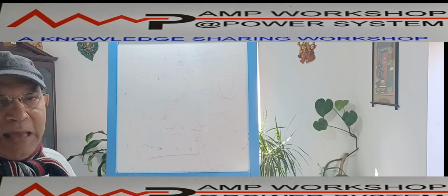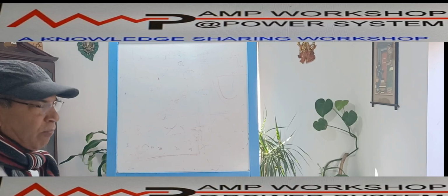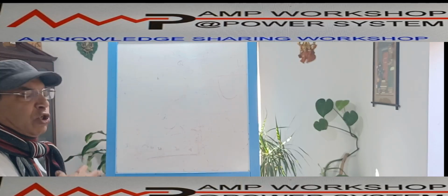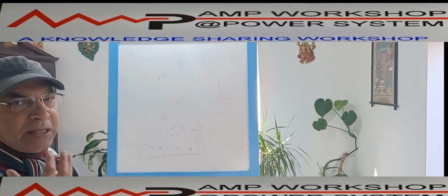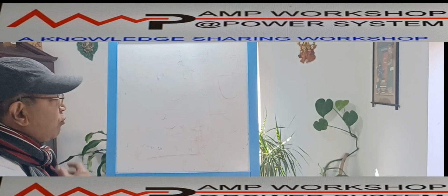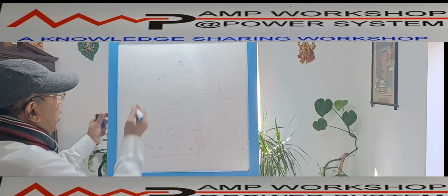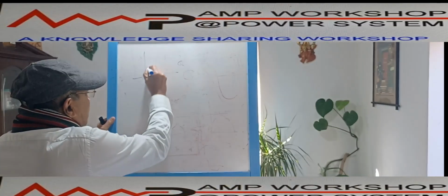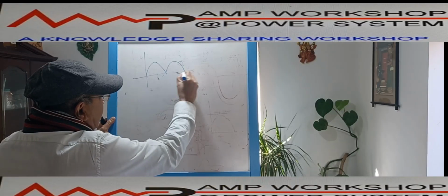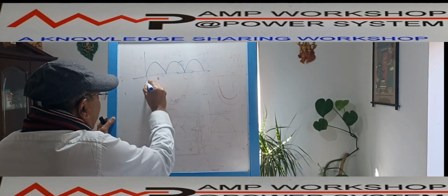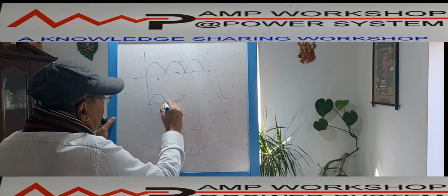DC voltage we call it average voltage. So what is the formula, what is the value? Given the input voltage, we get the required DC voltage. For that we need to calculate the output DC voltage magnitude. Now what about the shape you are getting here? You know this waveform, the full wave rectifier output we are getting like this, right? And the half wave rectifier we are getting like this. Half of the wave I am getting.